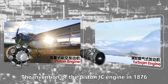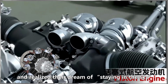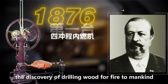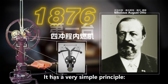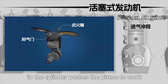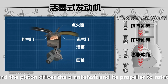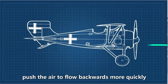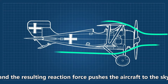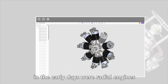The invention of the piston IC engine in 1876 brought a surge of power to mankind and realized their dream of staying in the sky, which was as meaningful as the discovery of drilling wood for fire to mankind. It has a very simple principle. Heat generated by the constant pressure combustion of gas in the cylinder pushes the piston inward, and the piston drives the crankshaft and the propeller to rotate. The propellers rotating at high speed push air to flow backwards more quickly, and the resulting reaction force pushes the aircraft to the sky. The majority of heavy piston engines widely used in early days were radial engines.